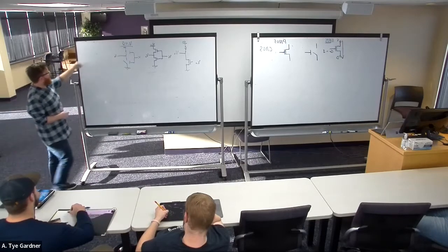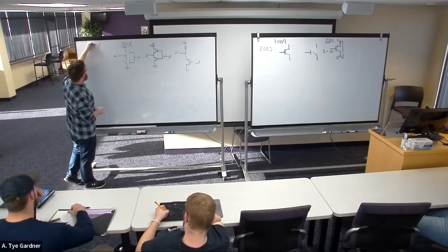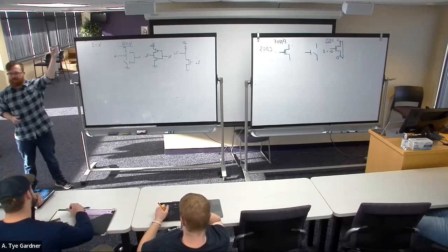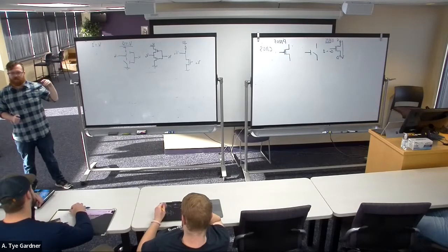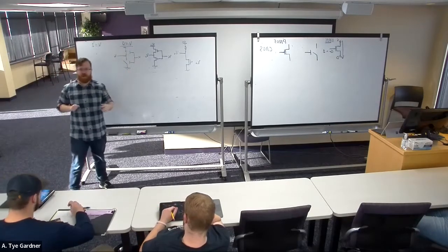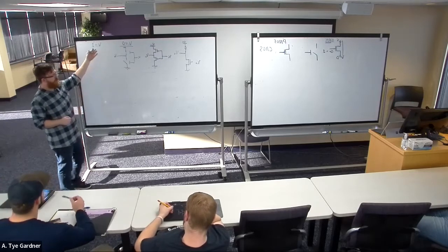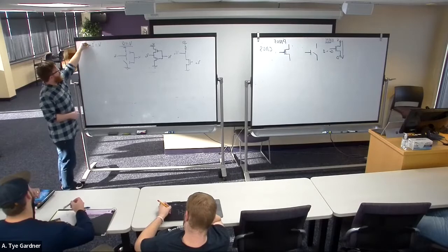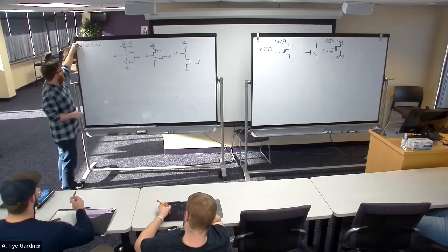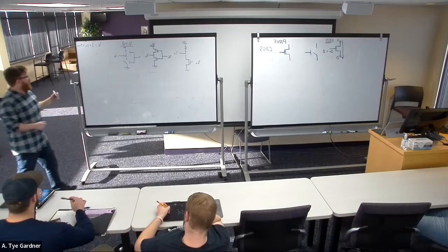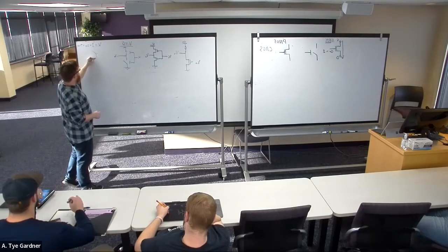Okay, well, let's look at the VI equals 1 case. And I don't mean 1 volt, right? I mean whatever the VCC is. The supply voltage tells me what 1 equals. So in this case, let's pretend VCC is 5 volts. That means VI is 5 volts. But this is 1, on, true, right? That connection. Well, all I end up with is the opposite scenario.